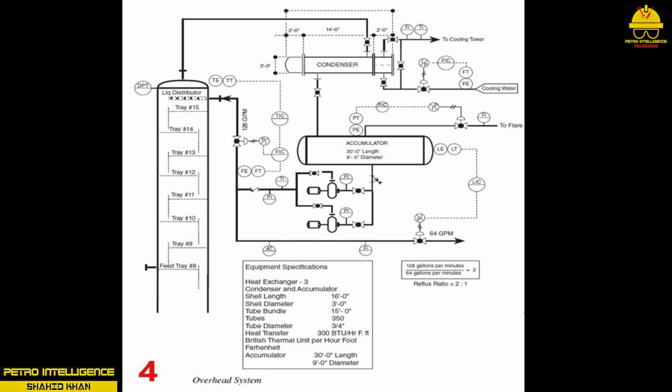The reflux pump is designed to discharge product to storage and to the top tray of the column. One control valve is mounted on the reflux line and another on the product storage line. Frequently, the reflux flow controller is cascaded to a master temperature controller at the top of the column. The reflux rate and cooling water flow rate to the condenser can significantly impact product purity and temperature. Reflux ratios will vary between different applications and are carefully calculated before the first pump or pipe is installed. It is important for a technician to understand the complex relationship the reflux ratio provides to a successful operation.